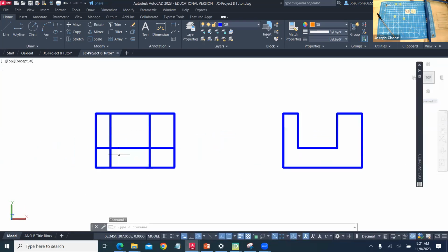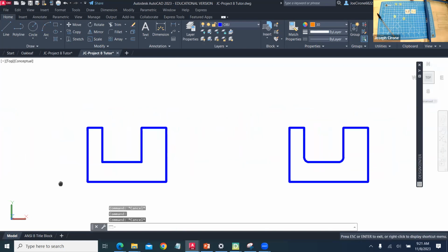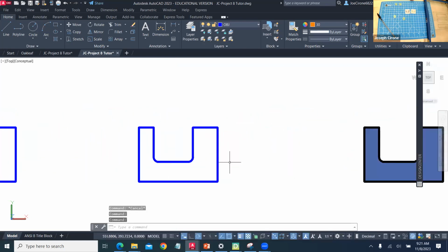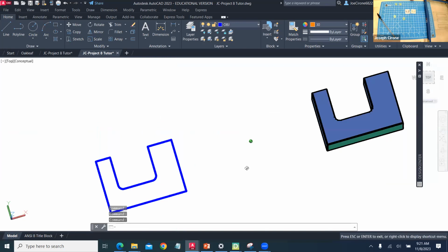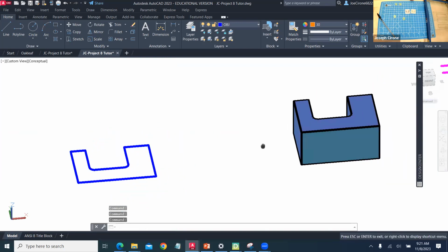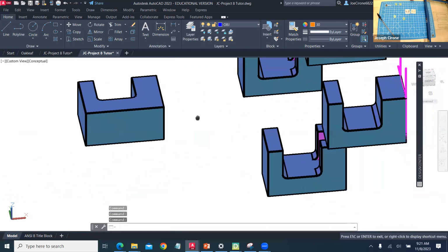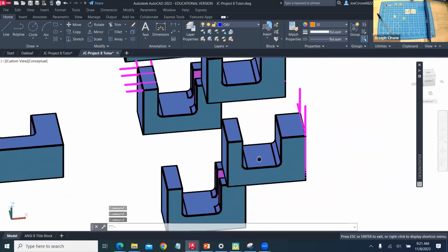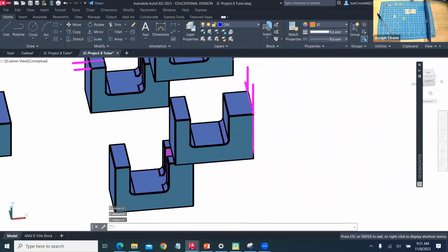And if we were to check those dimensions on our print, we can come into AutoCAD and we can click on one of the line geometries here. And then if we hover over the geometry, we can see that that is 80 millimeters. And then if we click with another grip, we can see that that's 55 millimeters. And so we roughed out the shape and we created the 2D geometry for that. And then what we do is we extrude that, rotate it, and create the geometry for it.